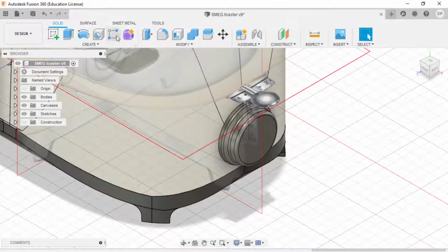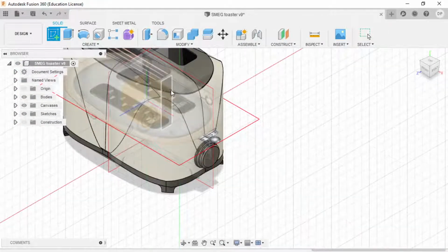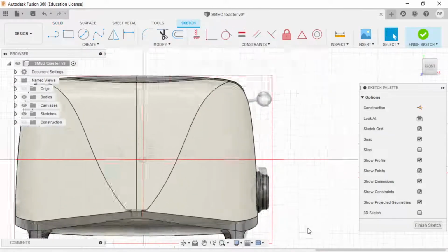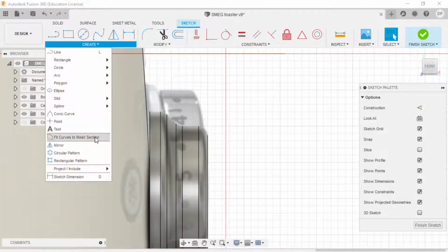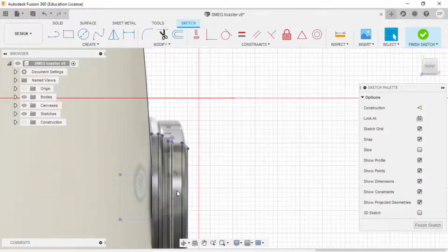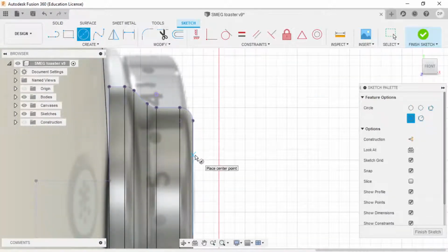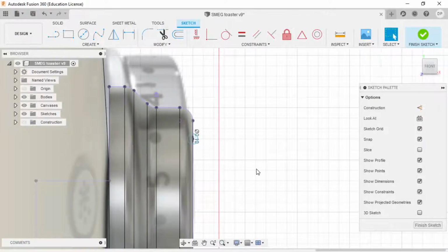So we will press this shape over here, not this, and we will sketch. We will include this geometry into the sketch. So I project this and this into the sketch. Give me the whole body. Thank you. We want to make a circle. I'm assuming it's going to be around like here. Let's make it 0.1. This over here is going to be part of the circle that's going to make the light part of our design.